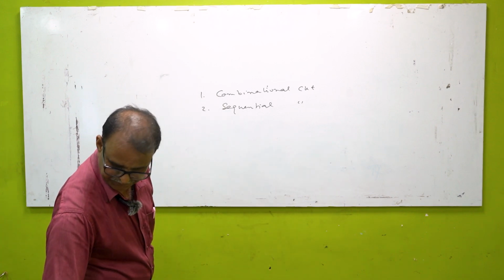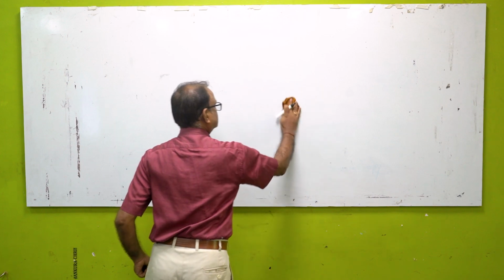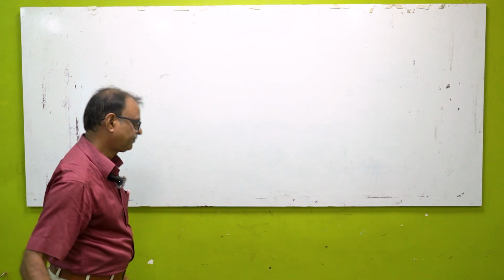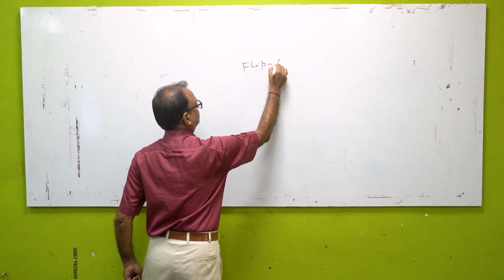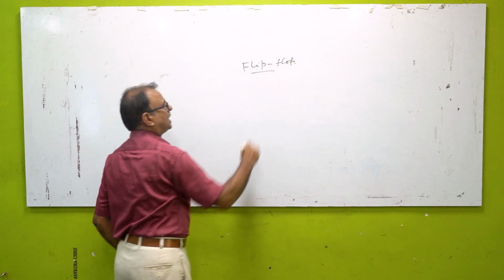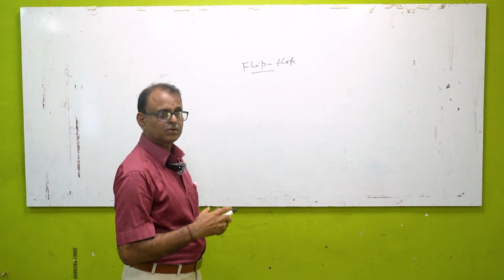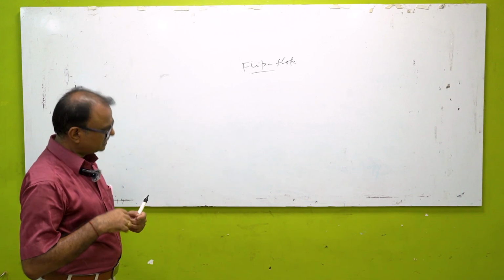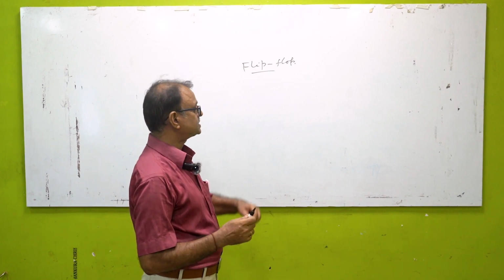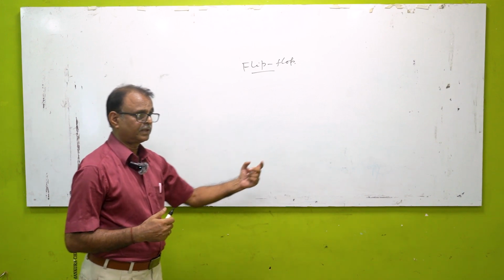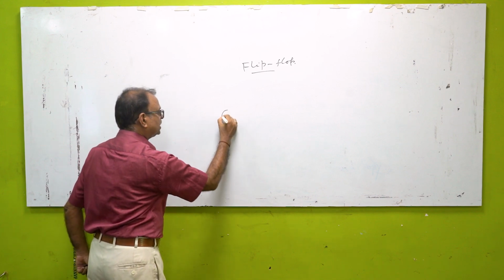So let's get started. What is this circuit? Sequential circuit's building block is flip-flop. A flip-flop is basically a multivibrator similar to an oscillator, and hence a heavy positive feedback is incorporated in the circuit. The circuit will not change the state by itself unless and until it is triggered to change so. Now there are two stable states as I told you.